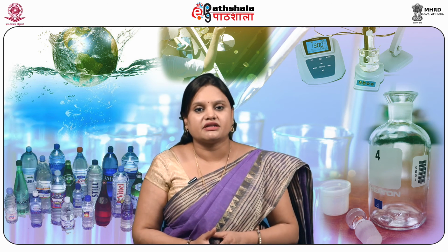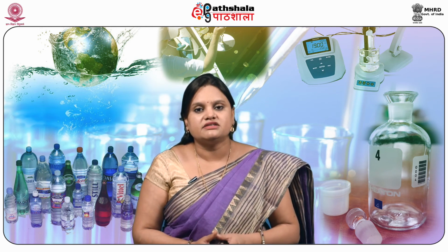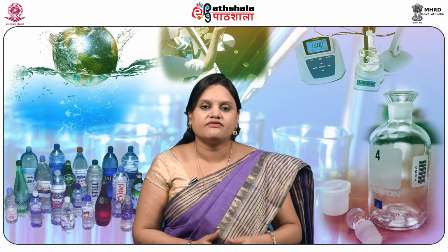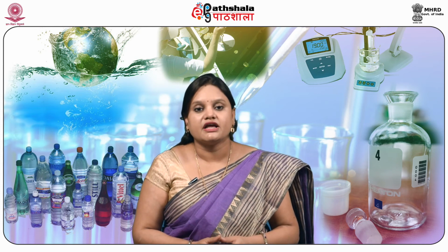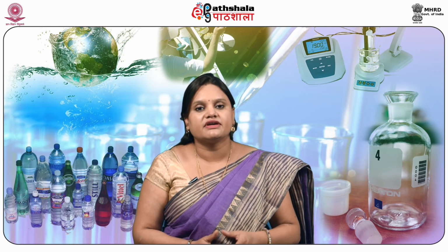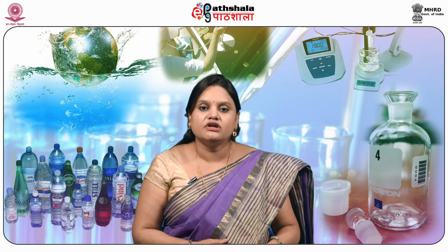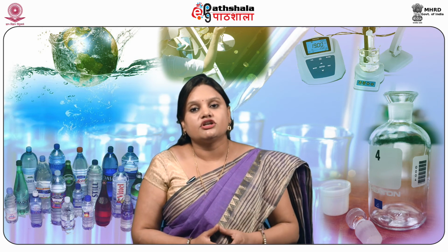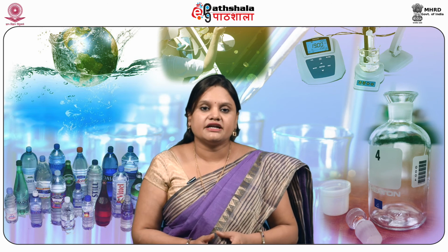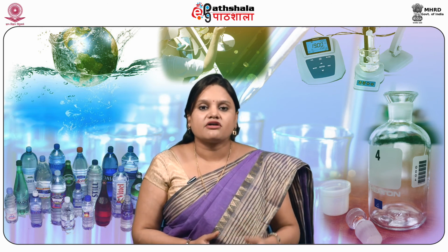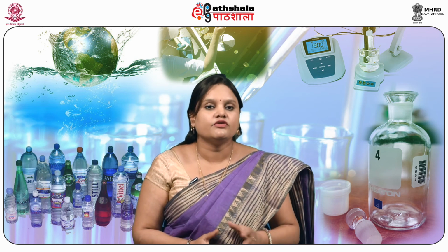Then the third important method is low NOx burner. A low NOx burner, or LNB, provides a stable flame that has several different zones for controlling the NOx release into the atmosphere. Then the next method is flue gas recirculation. In this method, the recirculation of cooled flue gas reduces the temperature by diluting the oxygen content of the combustion air and by causing heat to be diluted in a greater mass of flue gas.